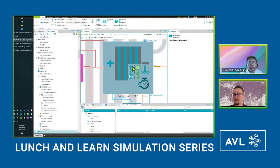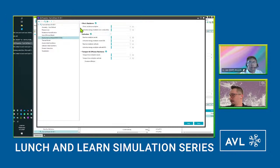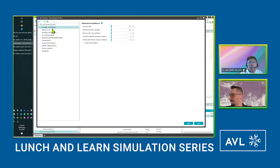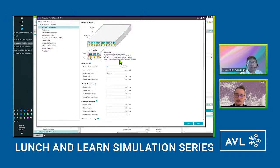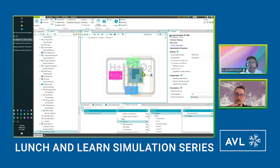In this case, it's a much simpler component than the complex geometry that Jun showed, but you will see a lot of similarity to what he has shown. Basically, the reaction equations and the reaction parameterizations are the same. It's a little bit simpler geometry-wise, just to put in the inputs, but you will get a simplified, fast-running version of it. We also have a workflow to transfer the FIRE M model, the complex 3D CFD model, into such a simple block. Basically, there's an automated workflow that allows you to do that.